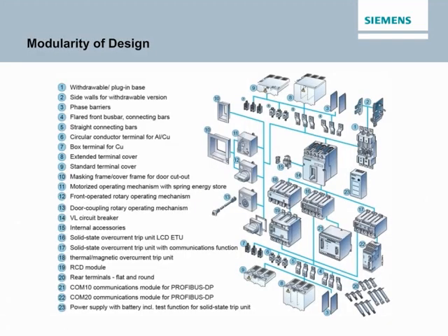One of the many aspects of the VL circuit breaker family is the flexibility of each VL circuit breaker frame to accommodate any of the following 3 available trip units: Model 525 thermomagnetic trip unit, Model 555 electronic trip unit, Model 586 electronic trip unit with LCD. The VL family also includes multi-case switches, motor circuit protectors, and other complete breakers with non-interchangeable trip units.